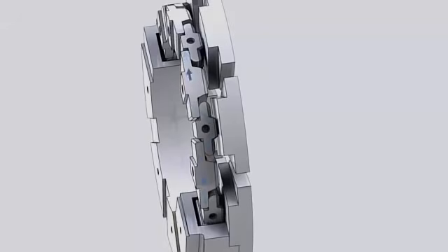The other edges of the lower leveling plates take part in supporting the adjacent upper leveling plate on either side. As a result of this arrangement, any excess of thrust load on a single pad is immediately shared through the leveling plates, so that all bearing pads will automatically receive equal loading.